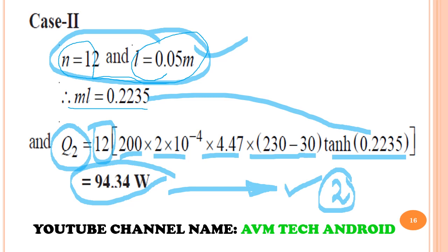It may be possible that when you are in a job in a company as a design engineer or as an expert, you have to select out of two conditions which you will prefer and why. So in this case you have to calculate all these parameters, and based on that give the conclusion that for case 2 heat transfer is more, so we have to go for 12 number of fins with length equal to 0.05 meter.